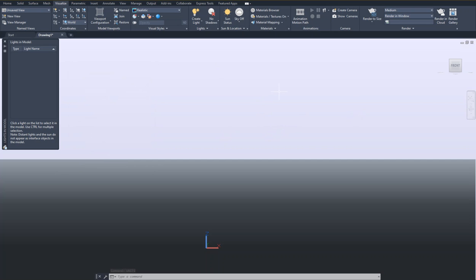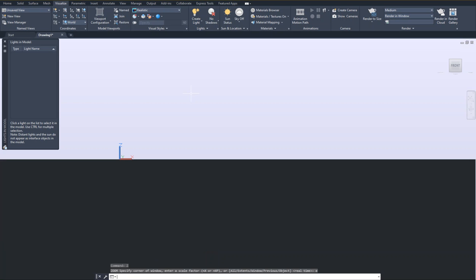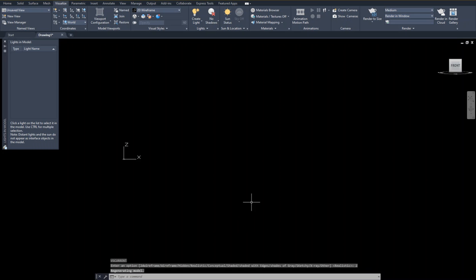The two things I want you to check when you start AutoCAD are units and limits. We're going to set our limits with the lower left-hand corner at 0, 0 and the upper right-hand corner at 12 inches by 9 inches. Then zoom, enter, E, enter. Also check the shade mode. Shade mode is the state of your screen, and right now we need a 2D wireframe. Later on, we're going to switch to three-dimensional views, but right now we only need 2D. This is a construction mode, so two-dimensional wireframe is good.